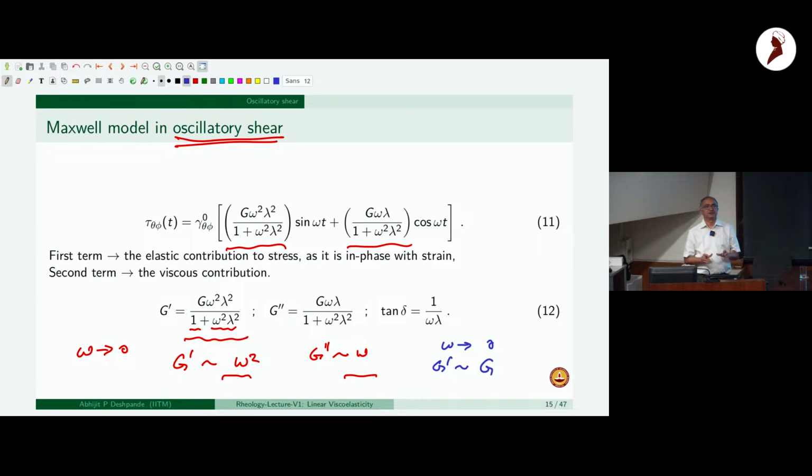So that's the elastic response, the so-called glassy state. So in the Maxwell model, basically you go from a perfectly viscous to a completely glassy material, and this happens in the Maxwell model within 2 decades. So as you go through about 2 decades, this transition happens in the case of a Maxwell model. Real materials don't show this change in just 2 decades.